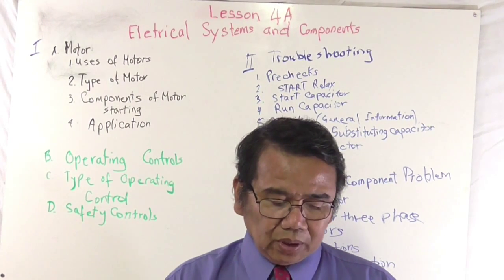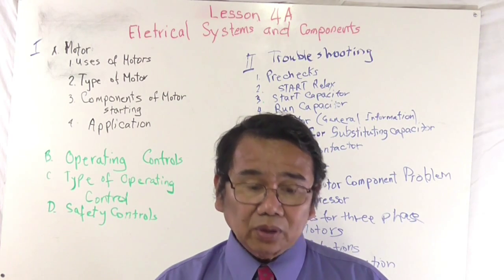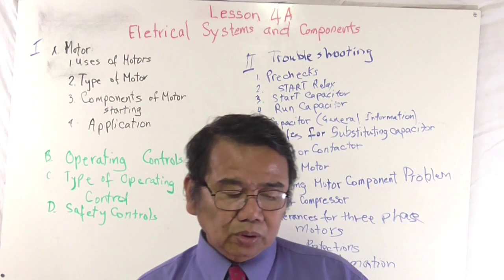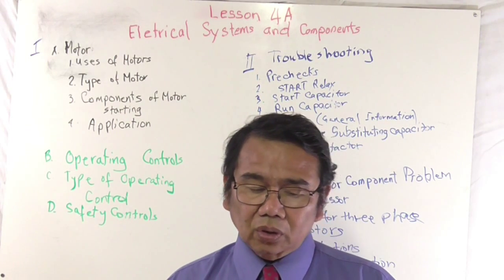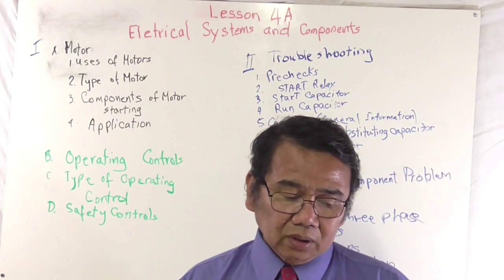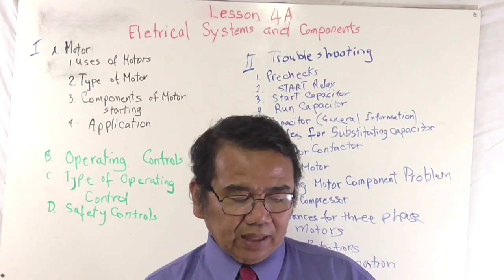And then we're going to go with a fan motor. Fan motor troubles: fan will not run, no voltage to motor, loose connection or broken wire, internal protector open or bad.